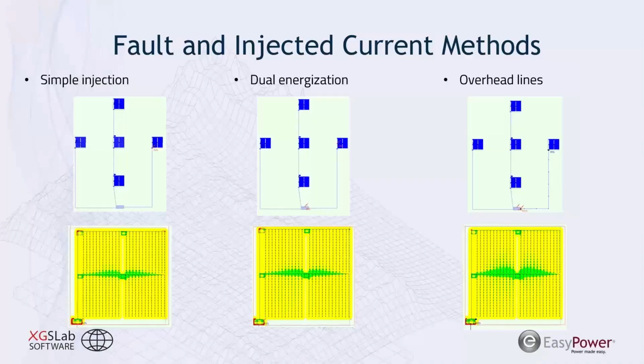the typical practice is that you want to have, we'll say, an A spacing that is equivalent to the dimension of your system. For photovoltaic systems, that's often not very feasible because you don't really have the ability to take a 3-mile long traverse if your system has a maximum dimension of 1 mile.